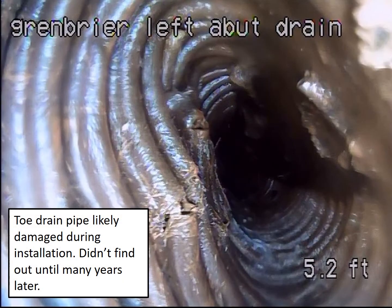Here's an example of that toe drain pipe I just mentioned that was a corrugated single wall plastic pipe, not really the best for buried applications for longevity. And the invert of the pipe is on the right side of the screen, so this is a 90-degree skew from the video camera, but you can see the crown of the pipe, the left side of the screen, was just split open and there was material entering the pipe. The pipe failed.